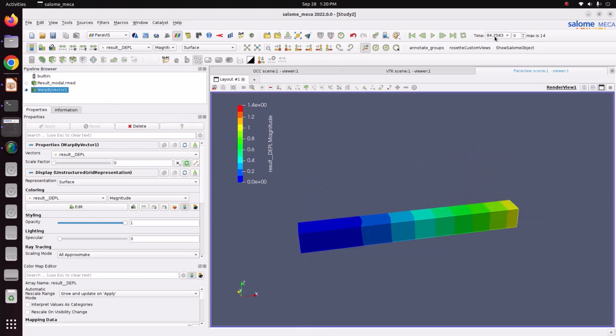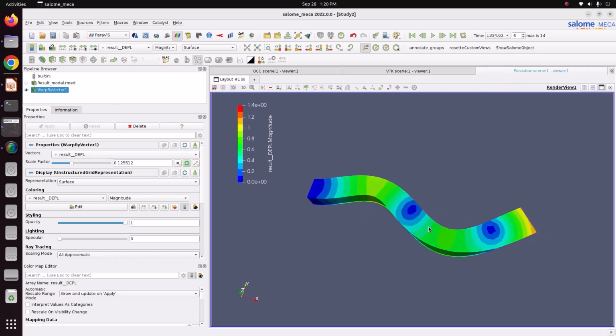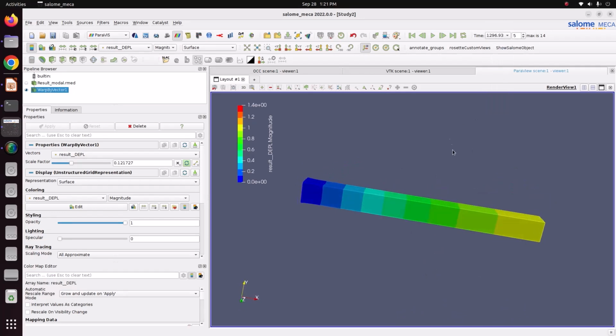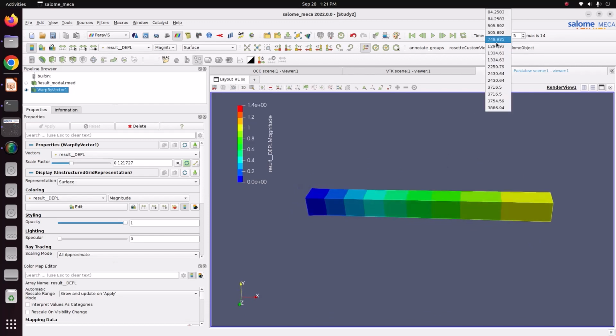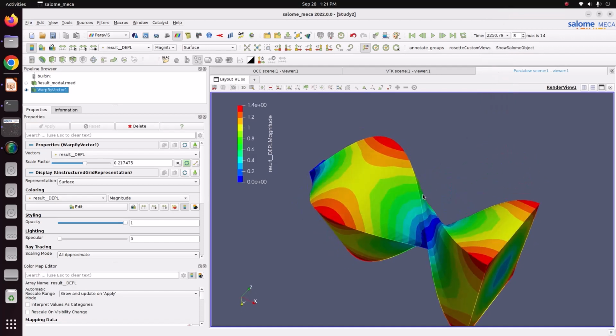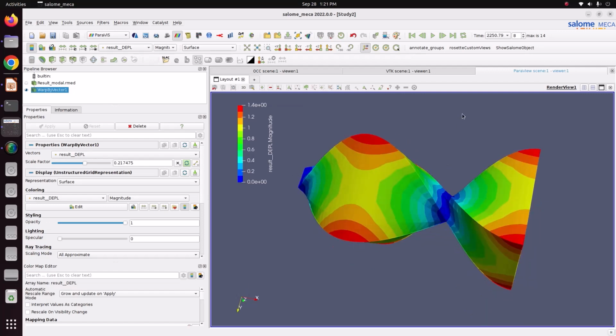These are multiple modes. We'll see one by one. So this is the sixth mode, which is tensile mode. It's extending and compressing. So the sixth mode is so rigid in that, so the frequency is coming around 1296. Seventh mode is a one node and two node. Two node it's actually bending. 8th mode also bending. 9th mode is a twisting mode with one node. There are two positions, here and here, where it's twisting.